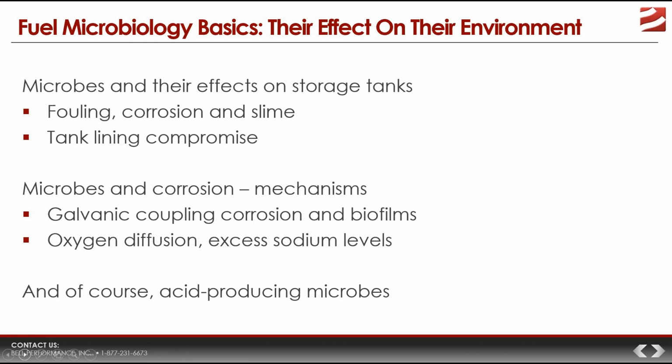If you get one little pinhole compromising the tank lining, it's plenty big enough for fungus and moisture to go into that pinhole. Now, the moisture goes into it, and then when the temperature goes up, temperature goes down, the moisture will expand and contract, expand and contract. Over time, it will start to compromise or delaminate the lining, cause it to become debonded from the tank shell. It's going to blister. It's going to peel away.